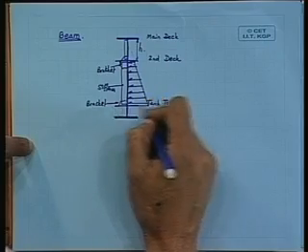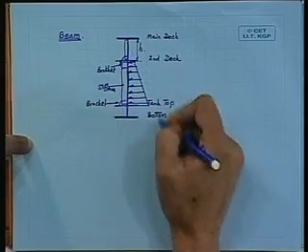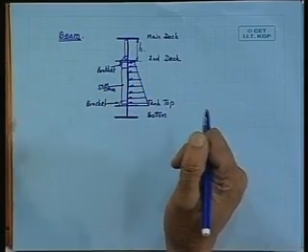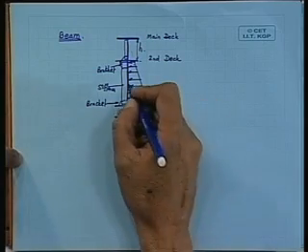and then we can also superimpose the stresses calculated on the basis of in-plane forces. But yes, when we do a detailed analysis, at that time an attempt is made to take all the forces simultaneously to get the true nature of the stresses in that particular structural element. Right. Now, here my primary member is between the second deck and the tank top, because the span is more and the load is of this nature.